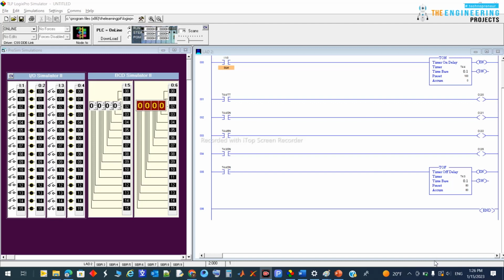In this session, we have had three types of timers, or three techniques of timing, and we have talked about the TON timer, which is the on delay timer, TOF, which is the off delay timer, and also we have shown two main techniques for cascading timing and for how to reset the cycle based on the timing by resetting the input of the timing technique.